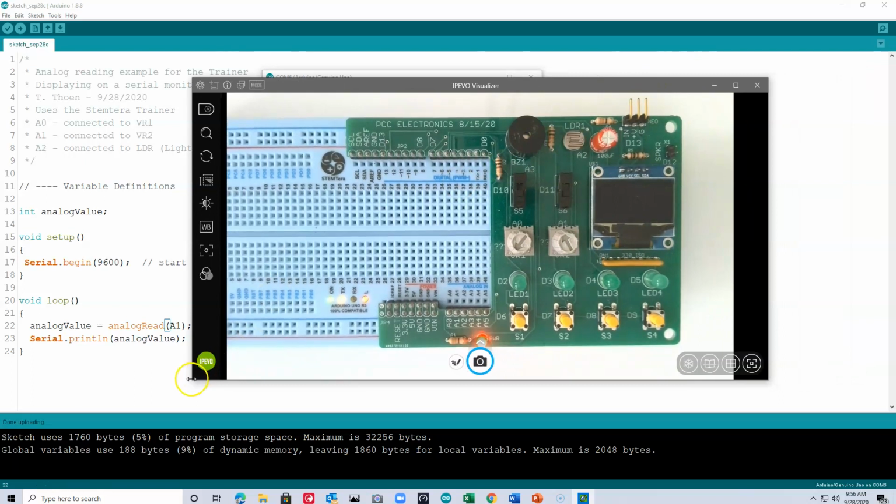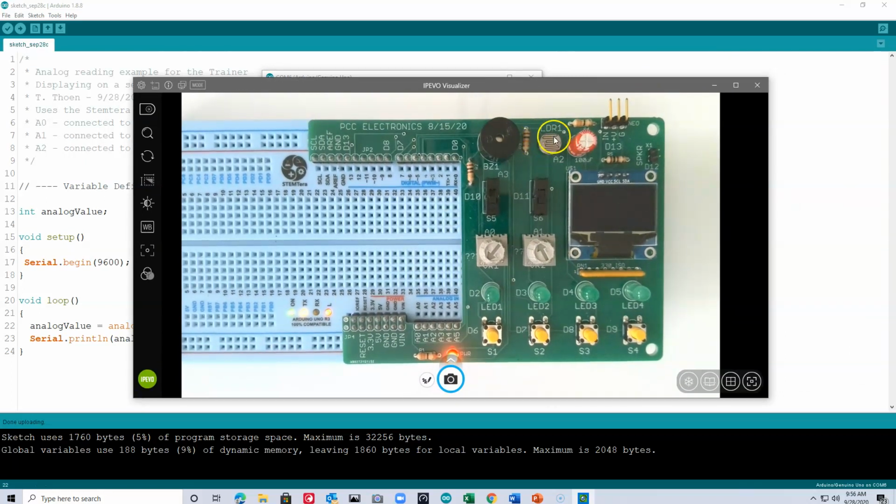It's this kind of funky-looking two-leaded device that has usually these kind of squiggly lines on it. And what it is really is a semiconductor material, and almost all semiconductors are sensitive to light. What's interesting is LEDs, which we think of as outputting light, are also sensitive to light. You can use them as a simple light sensor. But these ones specifically are used for all sorts of things. Turning on street lights at night, they have really large LDRs in them.